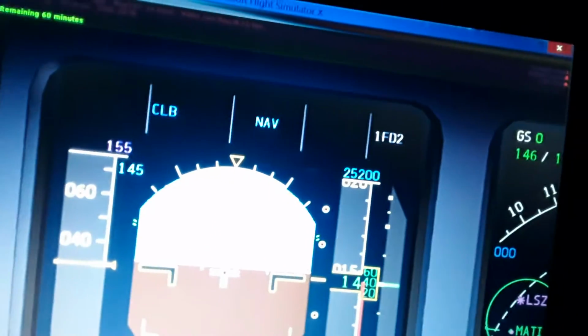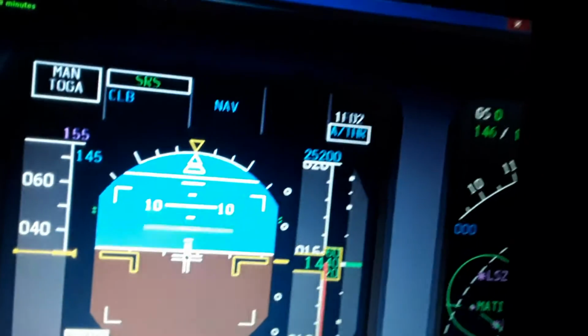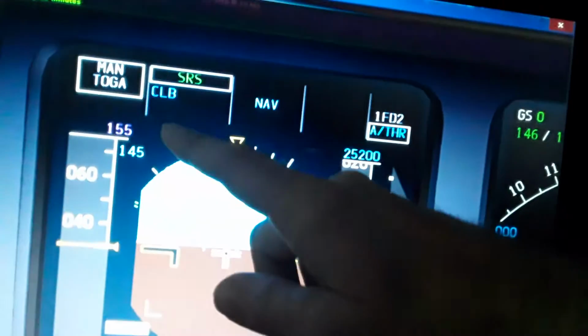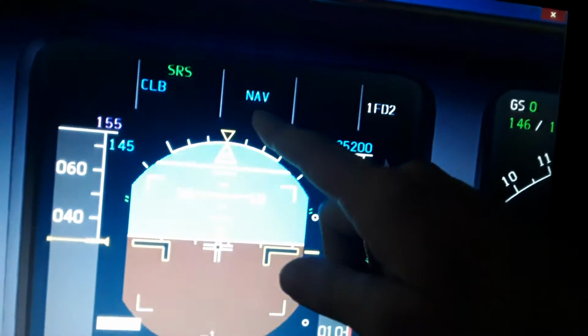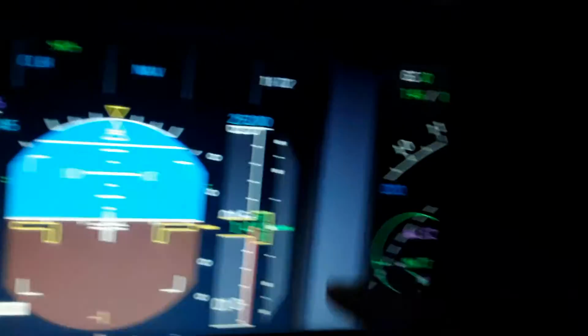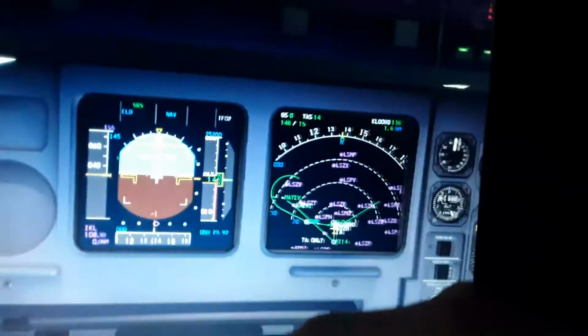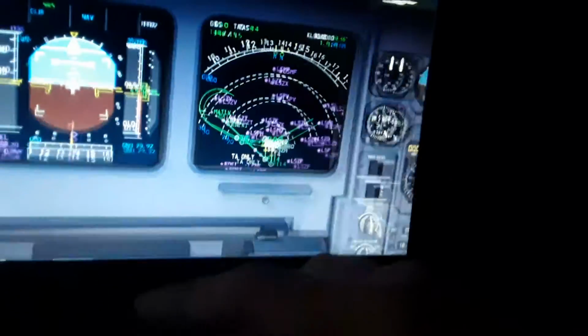The auto thrust mode here, our managed airspeed 155 knots for takeoff, our managed glide altitude, the SRS, which is also displayed, which is the vertical and the horizontal guidance, and the flight directors and auto thrust display. Here is the flight guidance of the aircraft. I'm gonna talk to you about later.